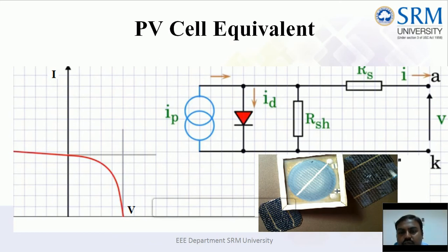and they can also model this as an equation by writing the diode's saturation current equation and solving this particular circuit with Kirchhoff's voltage law, to simulate and extract the IV curves. When I say IV curves, I may sometimes also say PV curves. You should not get confused. We have I and V to form an IV curve. A PV curve is nothing but a power and voltage curve. Whenever we have I and V, we can take the product and draw power and voltage curves.